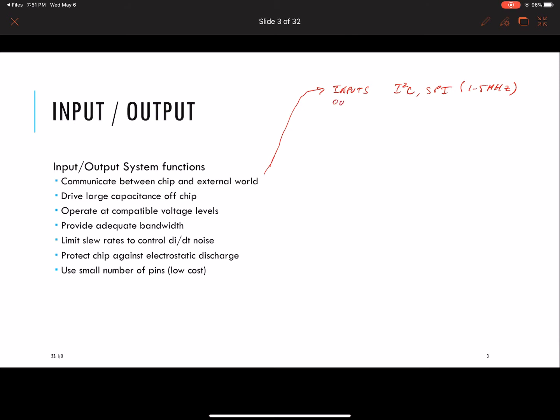And then on the outputs or inputs, there's the data itself, and then you might have serial outputs or inputs. These might be anywhere between, I don't know, like a gigabit per second to 50 some odd, let's say 56 gigabit interfaces to the chip. That's pretty fast. You might have memory interfaces like DDR interfaces, where mostly people are at DDR3 or DDR4 now. So these are the type, PCI, I don't know. There's a lot of different interfaces from low speed to high speed, but basically they are communicating with the rest of the world.